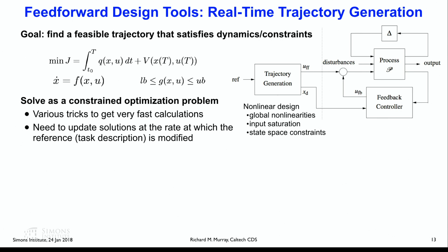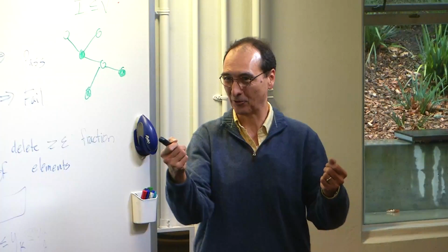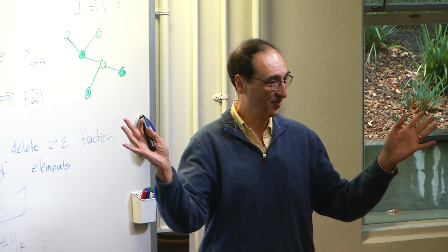And then what I'm really trying to do is regulate the state of the system to be near XD. And if that's small, that is, I had a pretty good model of the system and the disturbances don't take me too far away from where I expect to be, then I can linearize the dynamics around XD, and I won't get very far away from it. If the controller's doing a good job, it'll keep you near the thing that allows you to make the assumption that you used a linear model. It's one of these circular arguments, right? I'm going to use a linear model to design a controller. If that controller's a good controller, it will keep me near the place where the linear model is valid that I used to assume I could design the controller in the first place. And that works, okay? So that's what everybody does.